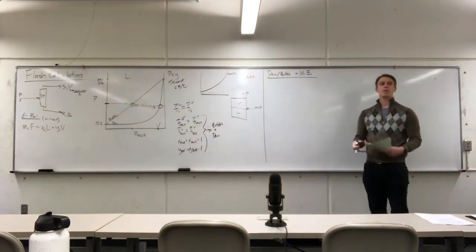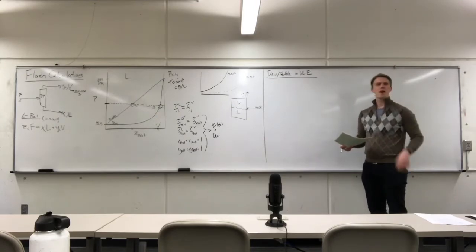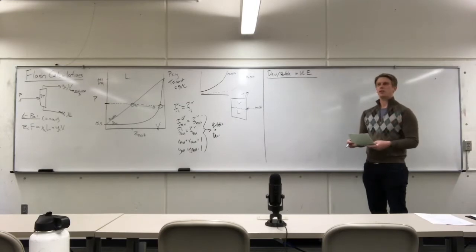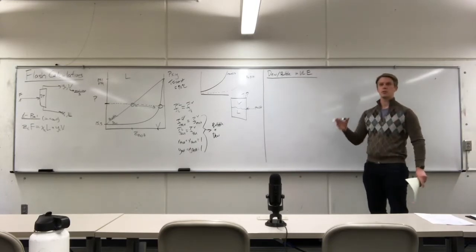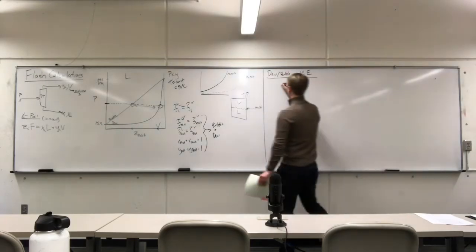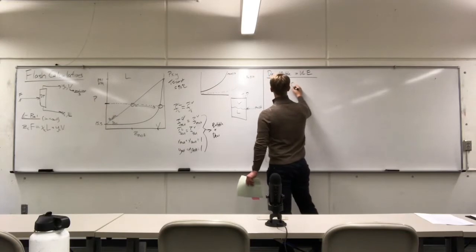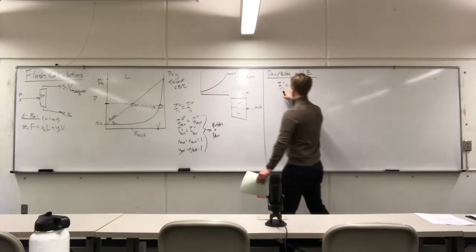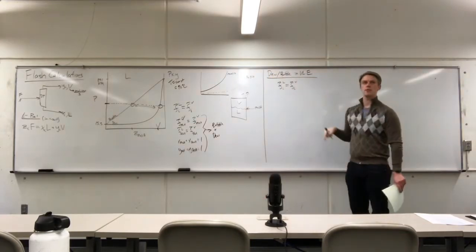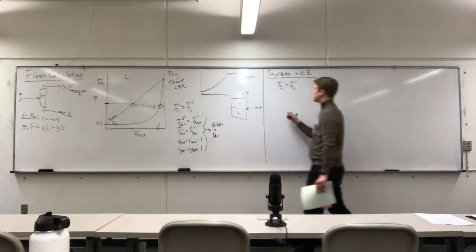Okay, we're going to treat this like it's an exam scenario. So if you read an exam question and you see the word phase, or what's the composition in this phase, that immediately cues you in that this is going to be a phase equilibrium calculation. So what is our starting point always going to be? Fugacity is equal, partial fugacity is equal. Now this is vapor-liquid equilibrium, so the partial fugacities across the two phases. One's going to be a liquid phase, one's going to be the vapor phase. Now we're going to generate Raoult's law.